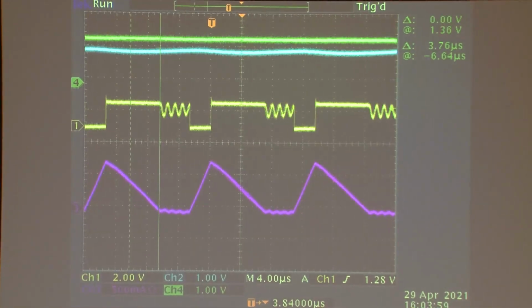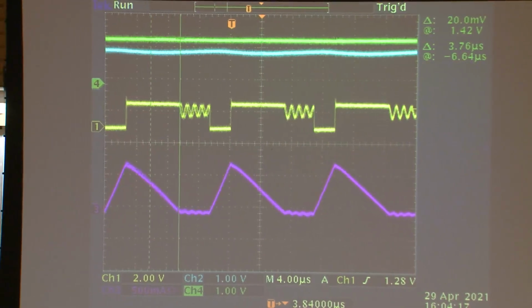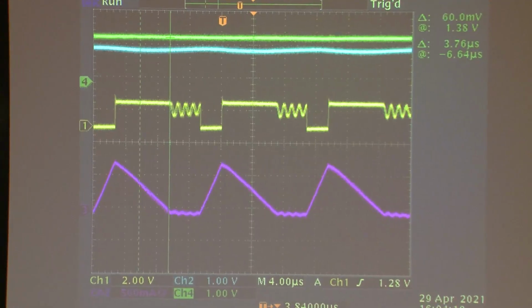In yellow, you can essentially see the switch voltage waveform, which is essentially this waveform moved up where this is 0, right? So in the first part of the cycle, you get 0 in the yellow waveform. The second part of the cycle, it's at V2, and then you get this time period where you see this voltage ringing, okay? What the heck is that?